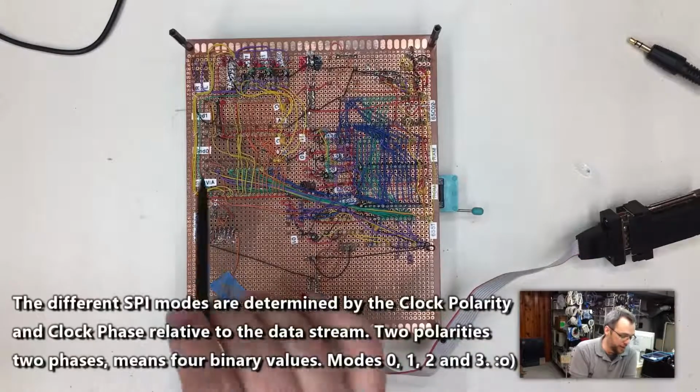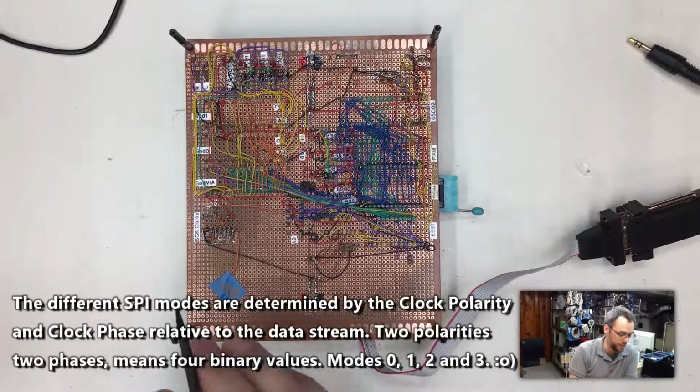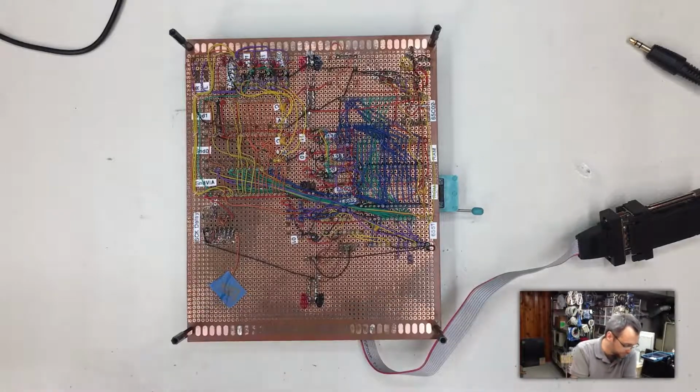Effectively, it doesn't work. But in SPI mode 1, that doesn't matter, because the clock's expected behavior becomes inverted, and so the data comes in at the right time, and it works just fine.